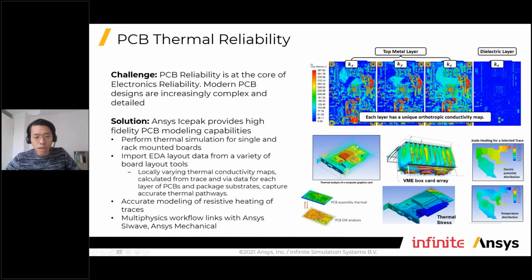And we know that Icepak is a full CFD solver. That means we don't just have the thermal distribution without air, but we also see how it interacts with the air around it. Then we can decide how we're going to cool our boards using different cooling strategies. This really gives you a tremendous amount of valuable insight on how to tackle thermal issues and how you can improve them, maybe by just separating your devices, or by changing the dimensions of your heat sinks.